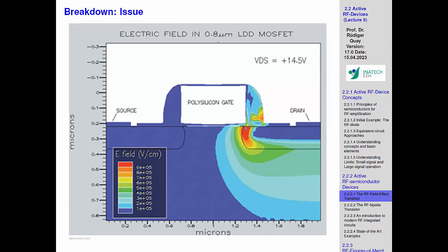And why is the E field concentrated here? Because you have that strong step of the P versus N region, when it goes from the P-doped region of the gate region to the N-doped. It's like a diode, which is a very localized jump in the concentrations, and then this looks like that. So this is really killing silicon CMOS in voltage. And it would look the very same if we went out to 22 nanometers, and a much smaller voltage would be the same problem. So we have a significant voltage problem.